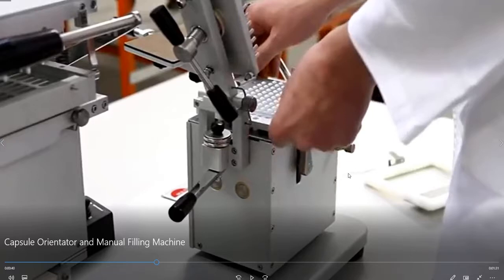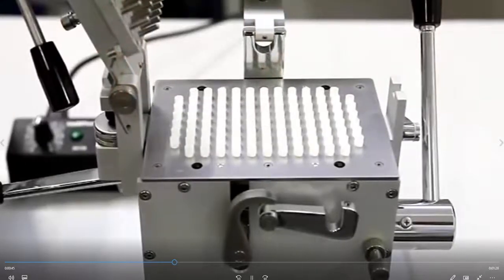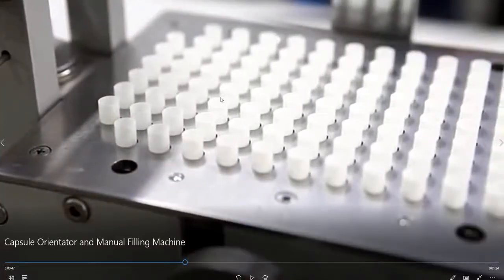He will sort of release the holders of the bodies, release it so that the bodies can lower down to allow the process of filling. What are these? Now what you see here are the bodies. Of course, you cannot fill them like this. You have to lower them and then put the rim of the tray to allow the powder to spread into the bodies of the capsules.